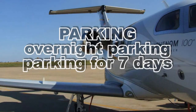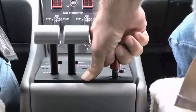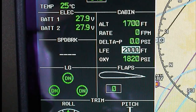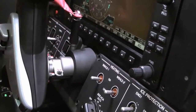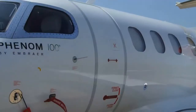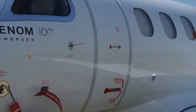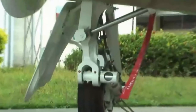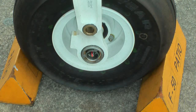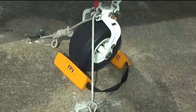Parking. Emergency parking brake: set. Flaps: up. Gust lock pin: install. Doors: close. Landing gear safety pins: as required. Wheel chock: install. Covers: install. Mooring: as required.